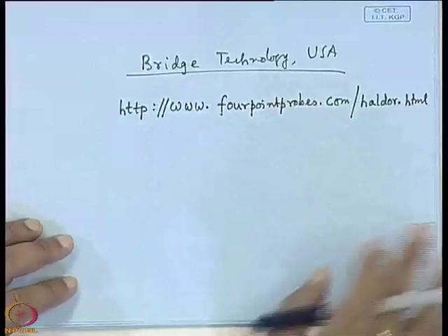So, this is all about the 4-point probe. In a nutshell, for the 4-point probe you do not need any metallic or ohmic contact. You only have to pass some current between the two outermost probes and record the voltage between the two innermost probes, and you must know the thickness of the sample, that is all.